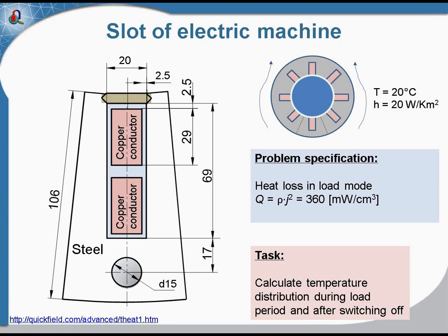This specific motor is not designed to operate in non-stop mode. It is designed to operate only limited time, and then there should be a period of cooling down to normal temperature. The insulation in the slot can withstand up to only specific temperature. So our task is to find what is the maximum operation time and what time is required to cool down the motor.